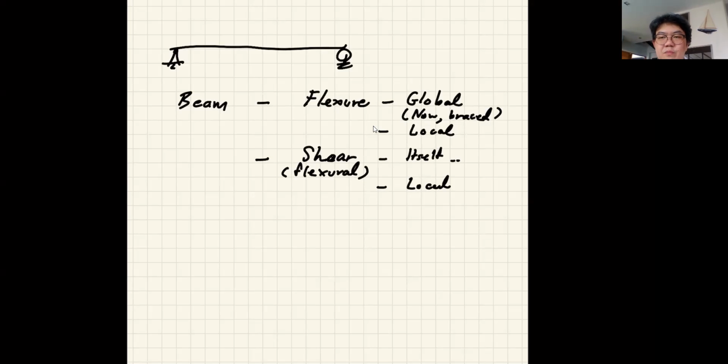So we should always check to make sure that, in calculating the capacity, we can use that formula 0.6 Fy multiplied by the area, which means the Cv is equal to 1. You should always check that. So that's two aspects. Now today you will be introduced to the third aspect.